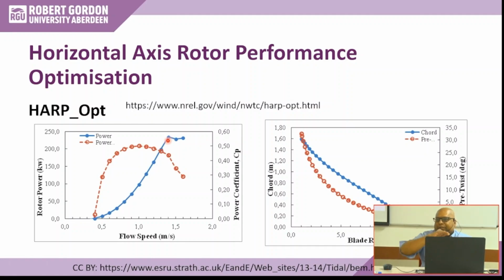After that, whatever the speed goes up, you control the turbine, you don't extract more power. You fix your maximum power at the rated power. Otherwise, you start to rotate violently and it may destroy the motor, turbine, everything, generator and gearbox. If the velocity is too high, you actually stop it sometimes to protect it. If the velocity becomes 5 meter per second, 10 meter per second, then you don't run it. So there is a rated speed, rated power.